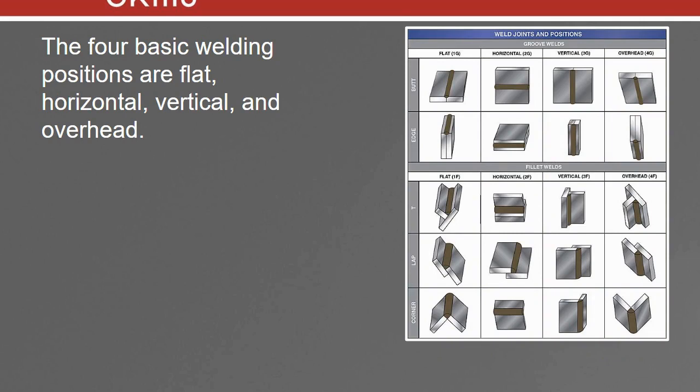We have 4 basic positions, and those will include flat, horizontal, vertical, and overhead. Now, I always like to tell my students just because it's above your head does not mean that it's overhead. You have to look at where the rod angle is pointing to.